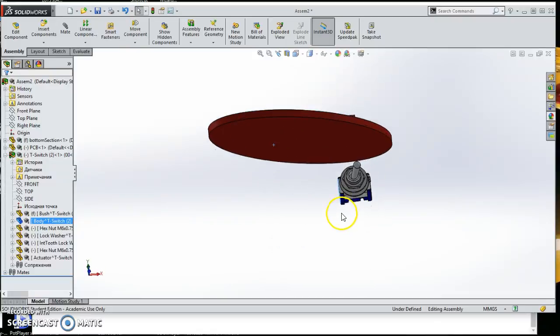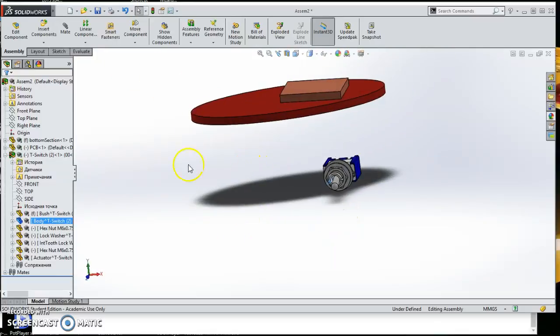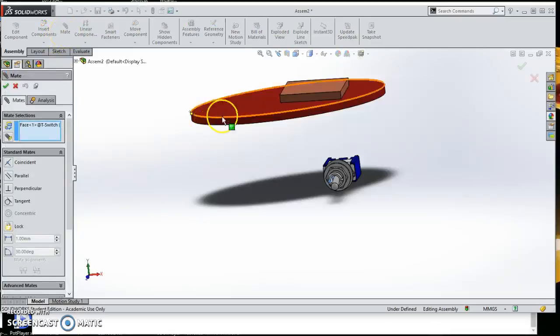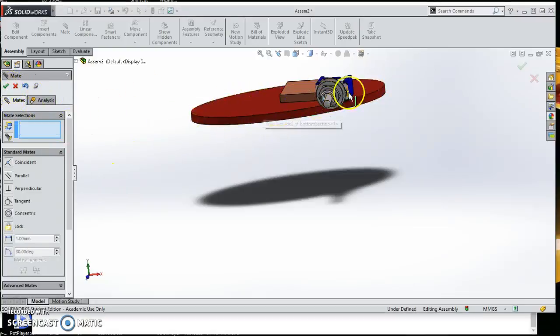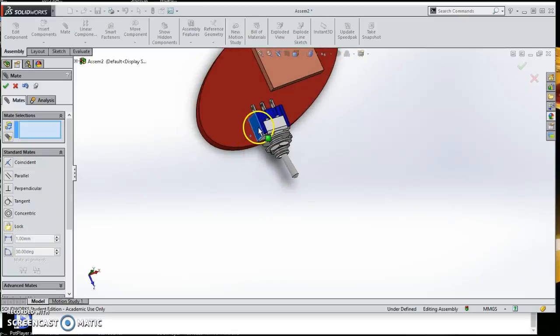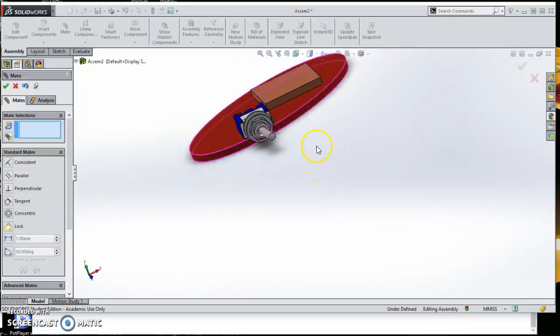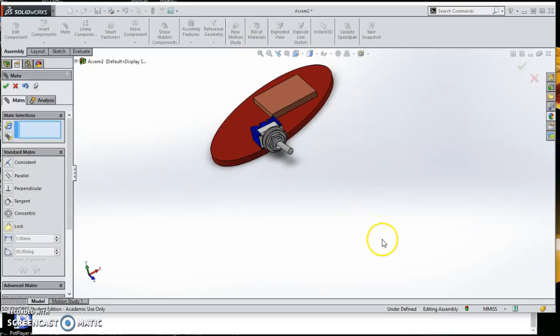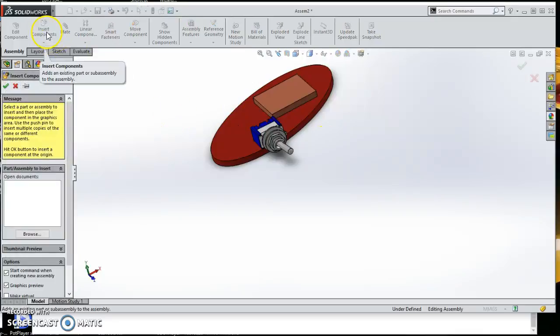And again, if there's a flat surface there that allows me to mate that, I can click there and then say mate with the top section here. Okay, I know that it's now on that plane there, so I can move it around on there, but I'll always know it will be level, and so I can mount that onto the board quite nicely, and that will be sticking out when I bring the parts up the way. Okay, so let's now bring in the middle sections. Remember the middle sections when you're bringing them in are 3mm each. Okay, so if you think